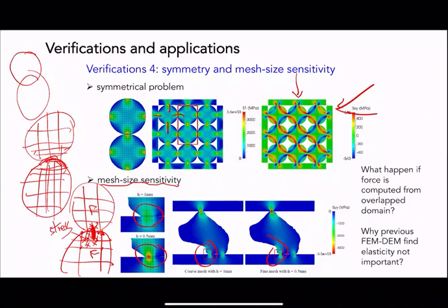So to capture this problem without the mesh dependency, even at the small scale, we may need a size-dependent damage model to help us overcome the mesh dependency, or at the very least, we need rate dependency to regulate the damage and the plastic deformations at the singular point. But here we just want to show that a small change in the mesh can increase the stress, and that won't stop.